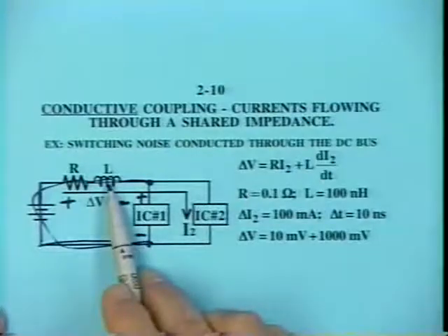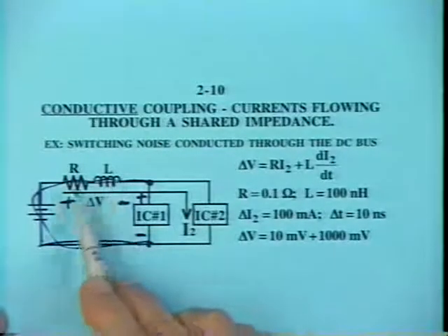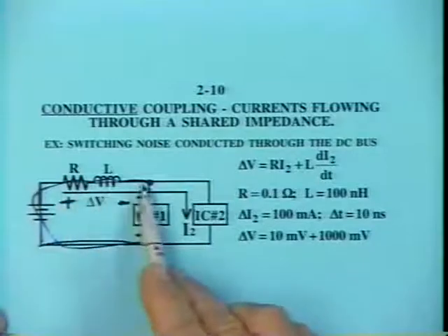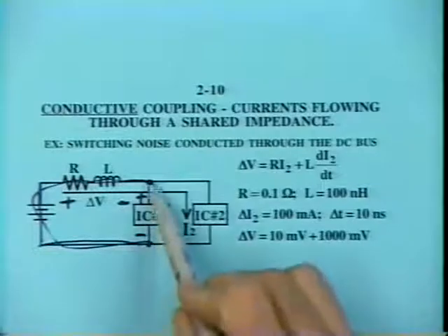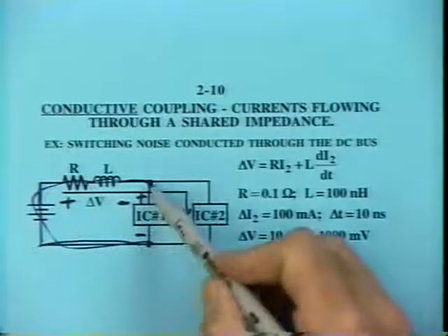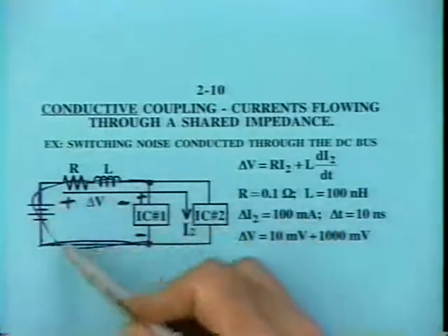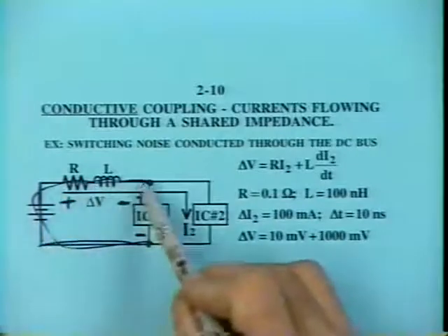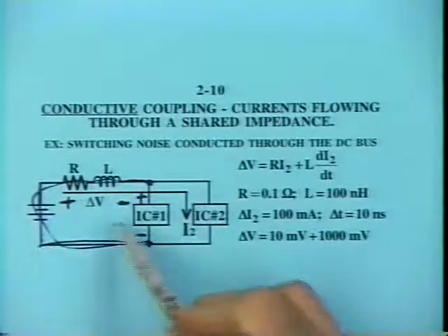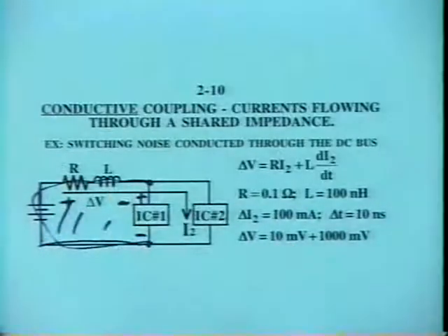What does that self-inductance represent? Well, that's not the self-inductance of the top wire. An individual wire does not complete a loop. It does not have self-inductance. But in this case, we can see there is a complete loop here. And you might have to say, well, exactly where is it closed? But we'll assume this dimension is small relative to the rest of this. It's not quite drawn to scale. So these 2 points are almost together. So we have pretty well defined a complete loop here. That loop has some self-inductance.